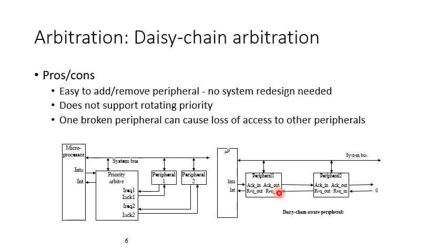The second disadvantage is that it only supports fixed arbitration. It does not support rotating priority arbitration. However, adding or removing a peripheral is very easy. We do not require any system redesign. Let's move on to the next slide.